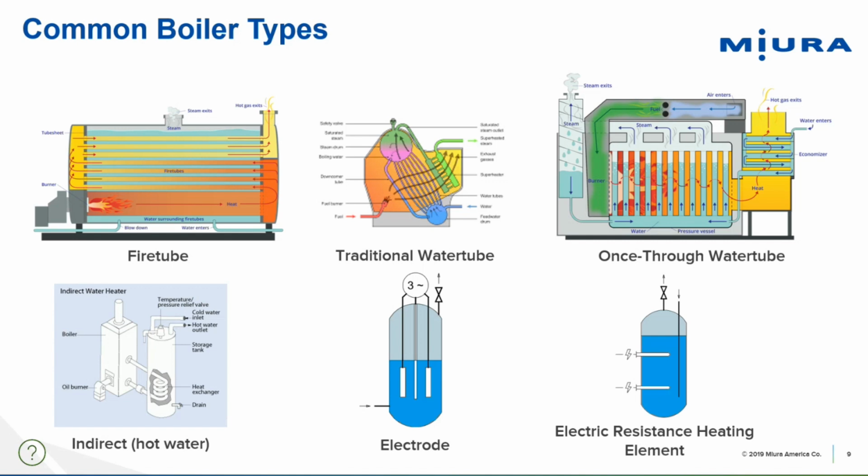Typically, your steam separation is occurring in a steam drum that usually has some heat applied to it as well. And then if there's a superheater, that steam passes into the superheater section, typically in the front part of the boiler here. But then the third type that doesn't really get mentioned often because it kind of falls under water tube is once-through